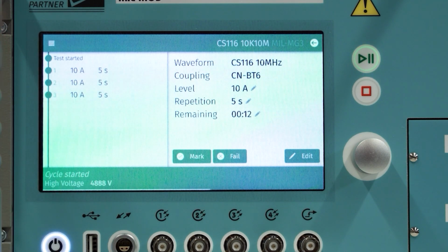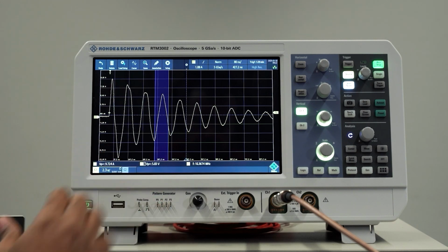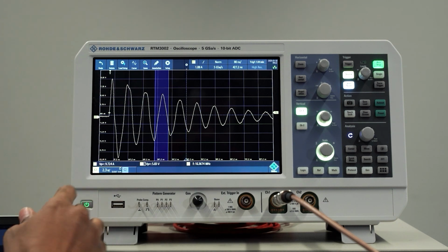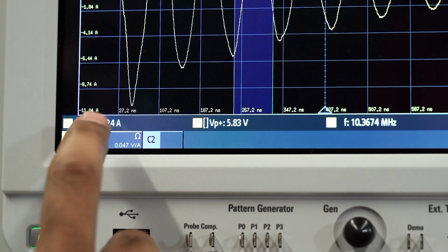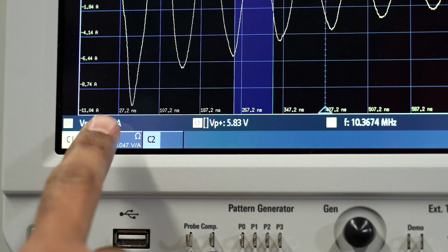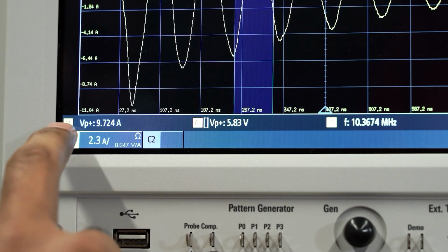So the next step is to enter the 3 parameters for the Q factor calculation in the DSO. As I said before, we have captured the waveform at 10 megahertz, and now we can set up the 3 parameters for the Q factor calculation, which you can see here. The first parameter represents the peak value measured by the DSO on channel 1, which is this one.